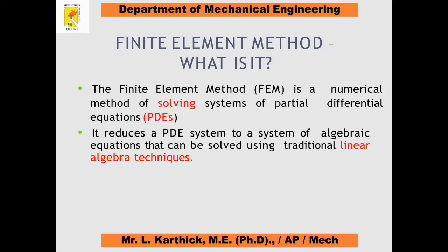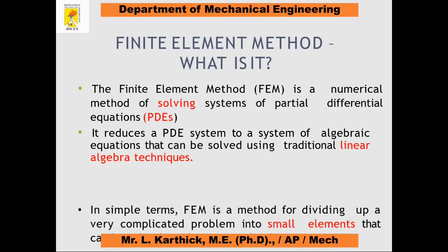It reduces the partial differential equation system to a system of algebraic equations that can be solved using traditional linear algebraic techniques. Since it is a numerical technique, we use matrix formulation for every expression or structure to find the displacement, stress and strain values for the component.